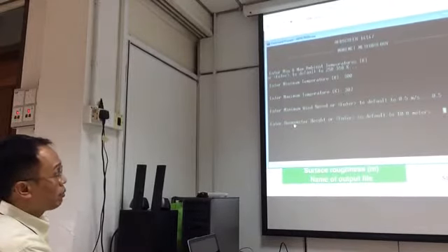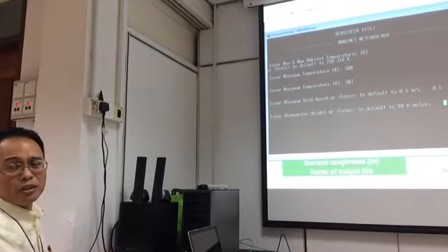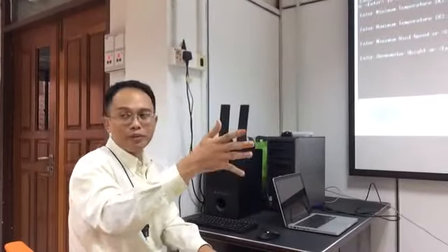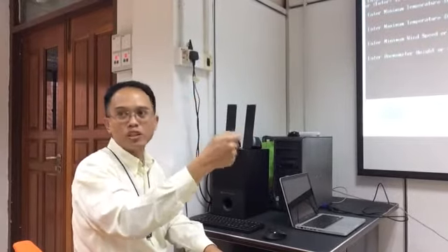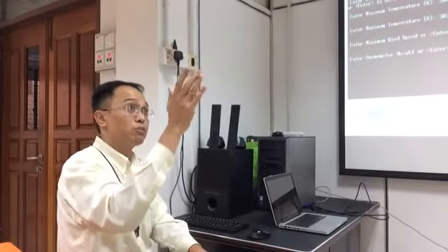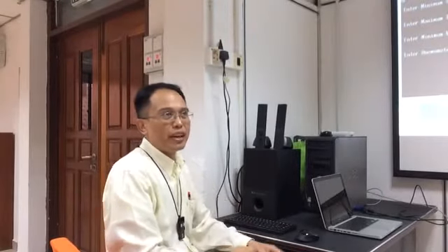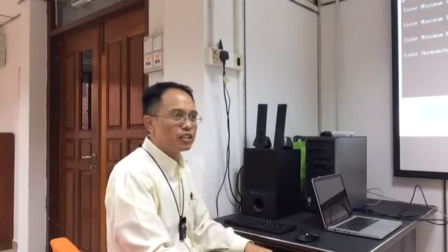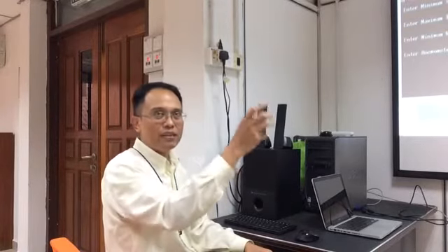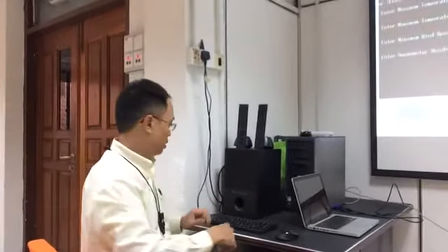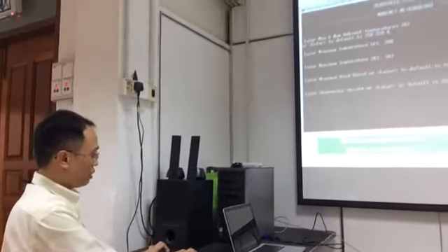Enter the anemometer height. Now this one defaults to 10 meters because it's the standard height of anemometer placement. An anemometer is the sensor to measure wind speed. If you notice any met station or even air quality station, if they have an anemometer, it will be placed about 10 meters from the ground. It's a standard height. So just type in 10 meters here. That's the default.